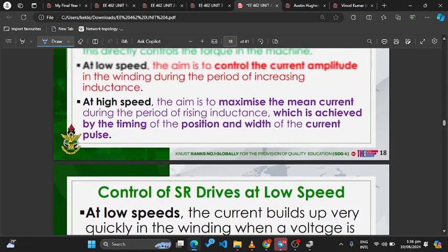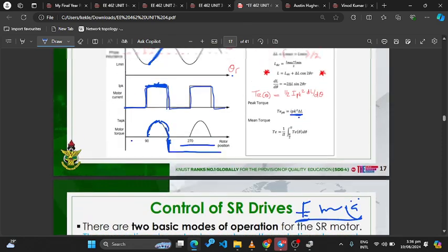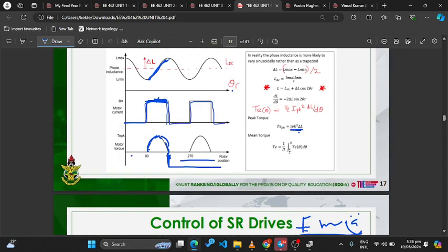Yeah. So if you want to control the mean current, to determine the mean current over here, it will be the area under this. So that means if you are controlling the width, the width of the pulse is just here. So you've heard about pulse width modulation. In pulse width modulation, all that you do is modulate the width of this pulse. Is that okay? Because modulating the width of this pulse also modulates the signal you are modulating.